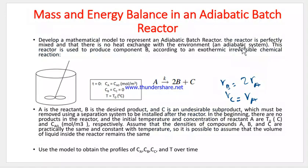Now, for the temperature term, we are asked to find the temperature model. You remember that it's energy in minus energy out plus generation minus consumption is equal to accumulation. Since it's a batch reactor, no energy goes in and no energy goes out. We are told that it is, what kind of reaction is this? We are told that it is exothermic somewhere. Let's look for it.